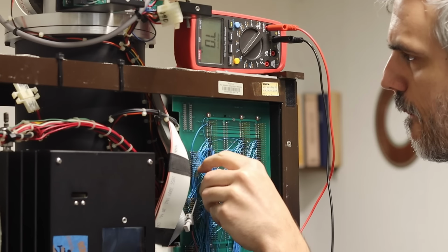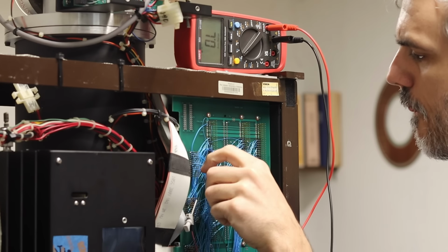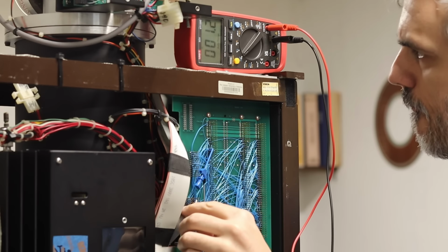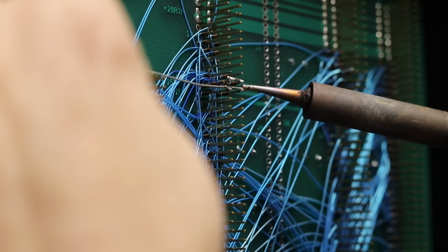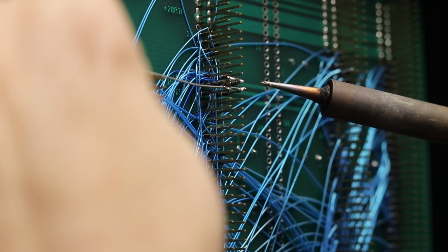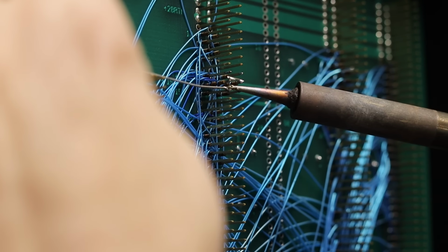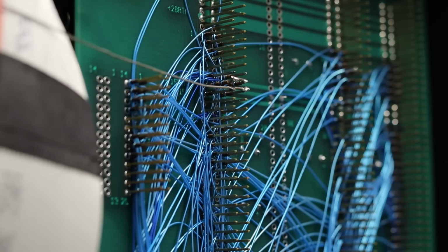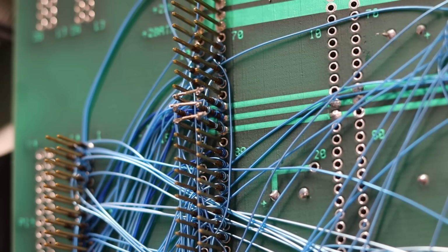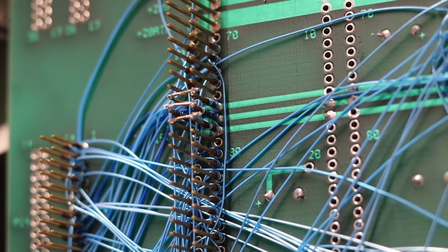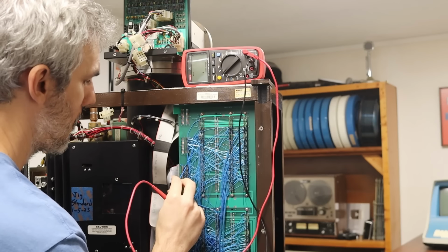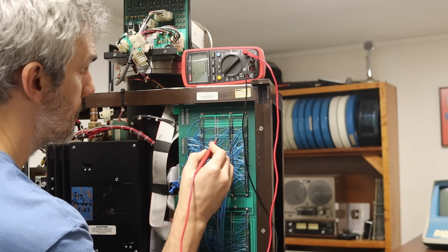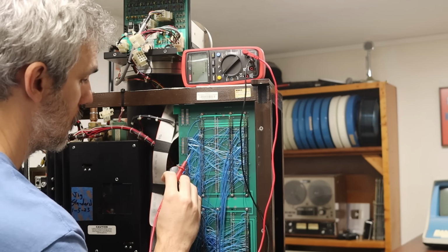Before I do anything, let's just confirm the pin numbers here and make sure I'm not doing something completely boneheaded. And yeah, we're on the right pins. I don't particularly like this solution, but I can't think of a better alternative. What I'm going to do is just tack a little jumper from pin to pin. This should be easily removable in the future with a little solder wick, but should also solve our production error here. It's not my prettiest work, but checking it with the multimeter, we should have our plus and minus 15 volt logic power making it to the motor control PCB up top now.